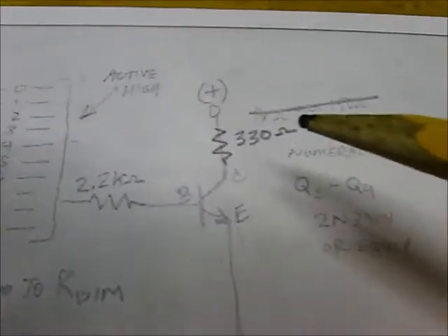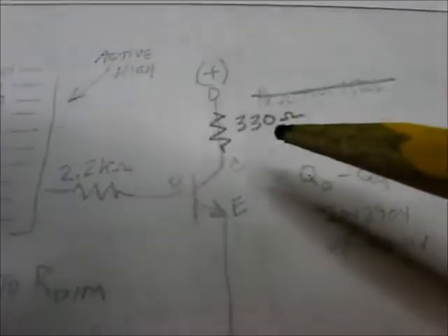So instead of the variable pot, I ended up putting a 330 ohm resistor in from the supply, which with the 9 volt AC adapter is running about 14 volts filtered and rectified. So this from the supply feeds the collector of all 10 transistors operating the LEDs. So total current limiting is the 220 plus the 330.